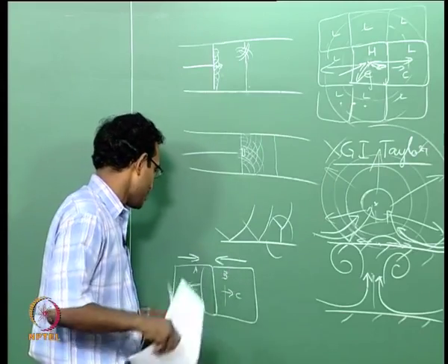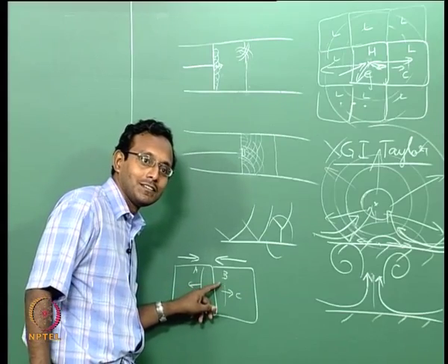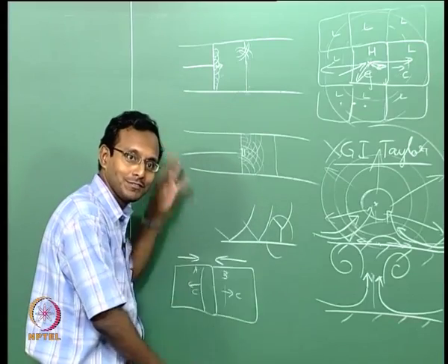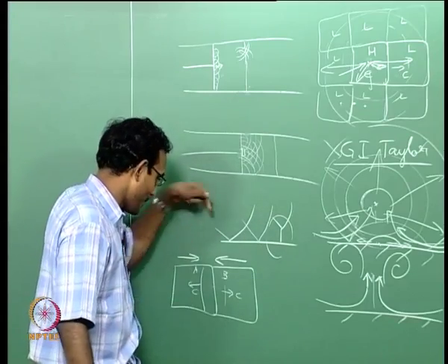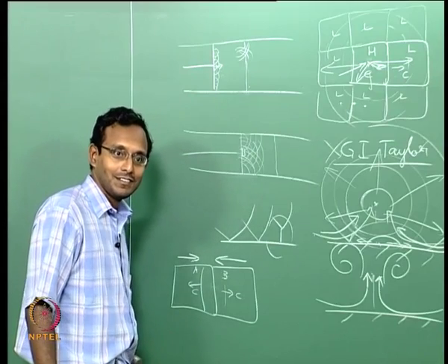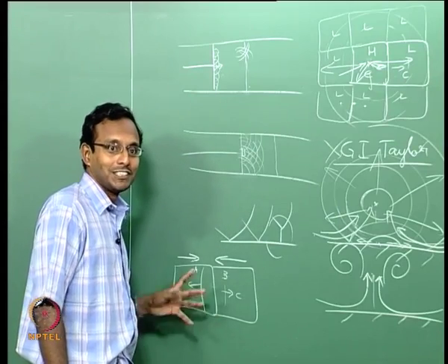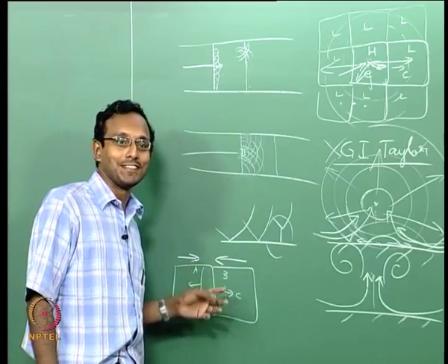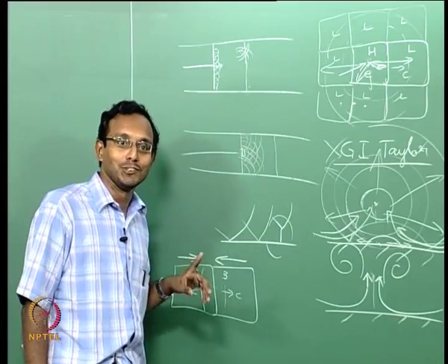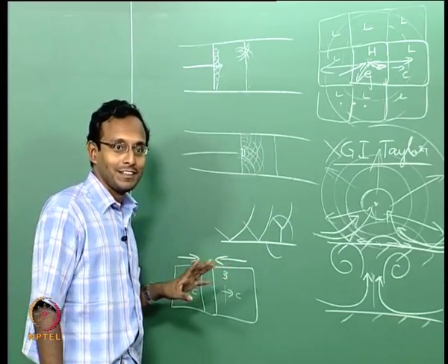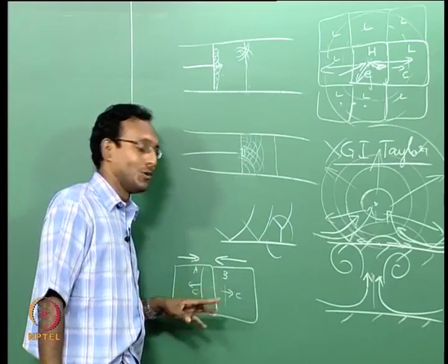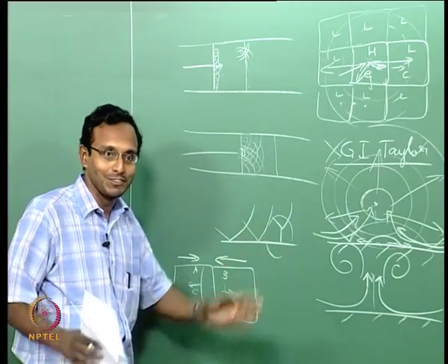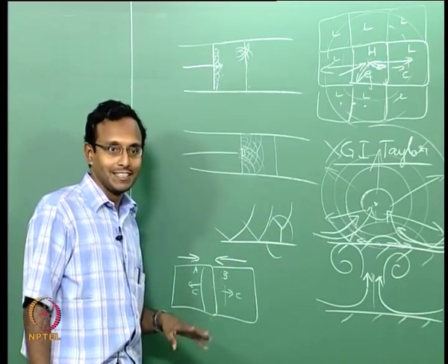Okay. Now I just talked about only the perpendicular component. Can they have this component up and down? Can A go up and B go down relative to each other? Yes, it can. Will it cause any pressure waves? This will not cause pressure waves in our gas dynamics. We assume no shear effect, right? We assume no viscosity. So these two will ignore each other moving sideways. They can just perfectly slip on top of each other. In reality, that is not the case.